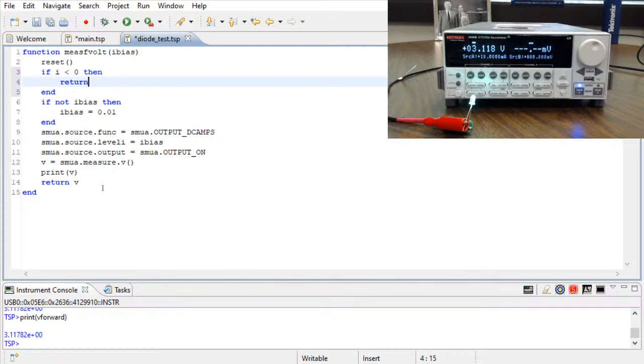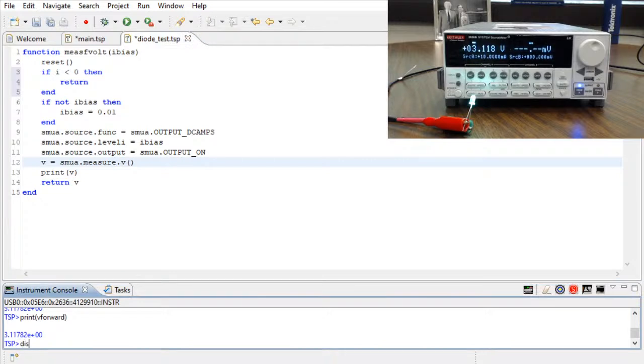So now we have this, let's try playing around with showing off these readings on the instrument itself. Let's try putting some things onto the display. There is, of course, a display library that allows you to control what's going on the instrument. So, for example, let's try display.screen, and we'll set it to display.smua, another constant there. Now we're looking at just SMUA of the instrument instead of that 2-channel setup.